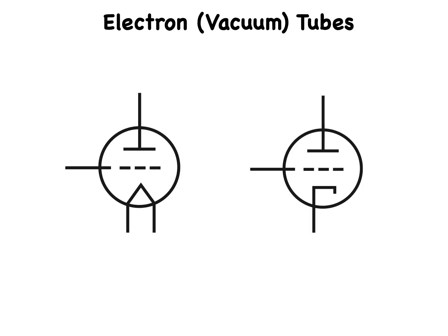This shows two versions of a triode vacuum tube, which consists of the same elements as the diode previously discussed, with the addition of a dashed line to indicate the grid. The tube at the left has a directly heated cathode, in which the filament and the cathode are the very same physical object. We apply the negative cathode voltage directly to the filament wire, no separate cathode exists. In the tube at the right, we see the symbol for a triode tube with an indirectly heated cathode. In this symbol, the filament is inside the cathode.